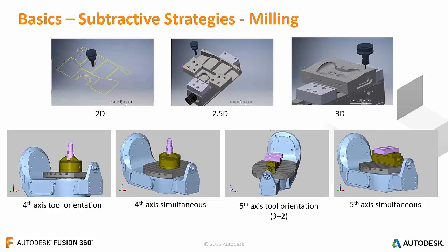Where we use that quite a lot is inside Inventor, using the new Inventor nesting utilities, where it allows us to take an assembly that's made up of sheet metal components. It will flat pattern those components and automatically develop out this particular profile for us, which we can then send to CAM. And you can see there's a very quick simulation there.